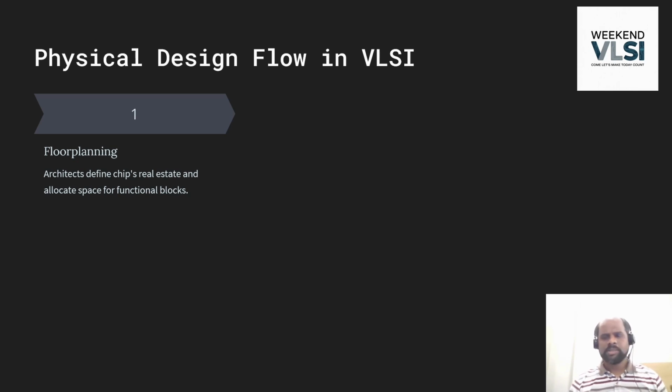Floor planning is done in a couple of stages. One is when you have your hierarchical block, you do a chip level floor planning, or partitioning, they call it. Once that is done and pushed into a block, inside the block you do block level floor planning. Now I am going to cover this block level floor planning. What are the different steps in block level floor planning?